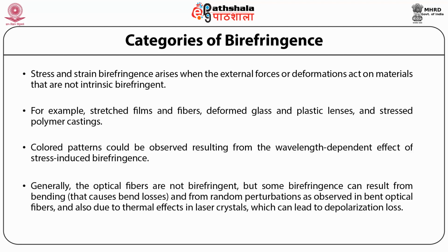Generally, optical fibers are not birefringent, but some birefringence can result from bending that causes bend losses and from random perturbations as observed in bent optical fibers, and also due to thermal effects in laser crystals, which can lead to depolarization loss.